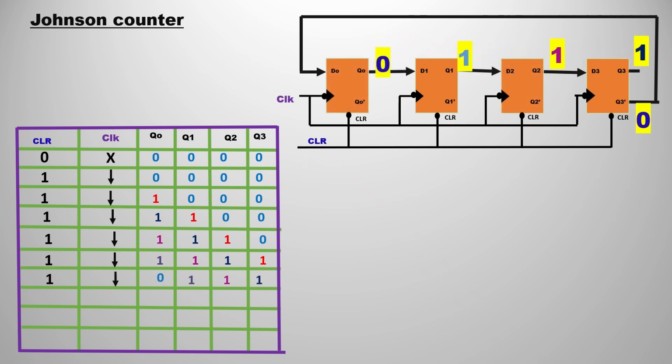You can see that with the feedback of Q3 bar, Q0 appears as 0 and the 1s shift rightward again. Again Q3 bar is 0, and again we move all the ones to the right flip-flops. We move things from left to right, and diminish the ones, and all the zeros come back, the first state again. I hope you can do the remaining 2 steps.